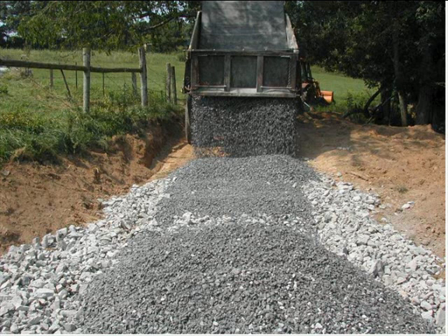Rock size and gradation should be the smallest mix needed to remain stable under prevailing flow conditions. Bigger isn't necessarily better for passage because of turbulence, and can also create problems for livestock. You may need to add sand or soil into the mix to seal the section to ensure that the stream doesn't percolate into the crossing substrate. In addition, smaller material increases bed diversity, chokes voids between bigger stones, and helps preserve passage quality.